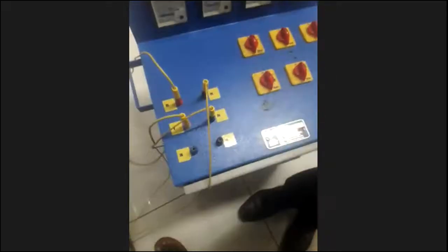Again, to measure the supply voltage, that means the primary side, there is a three-phase supply, so we are using one voltmeter having a range 600 to measure the supply voltage. See, this voltmeter can be connected at the output side of the auto transformer. That means I want to measure only the supply voltage, how much supply is given, for measurement of V1, the primary supply voltage. I am using one voltmeter having a range 0 to 600.